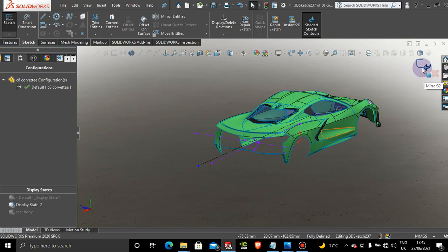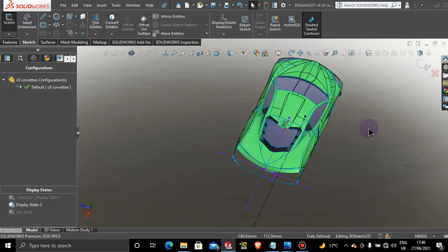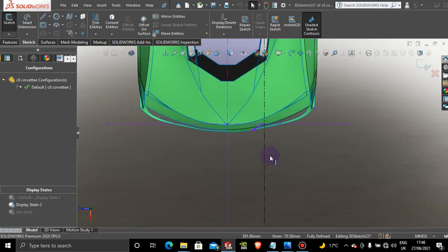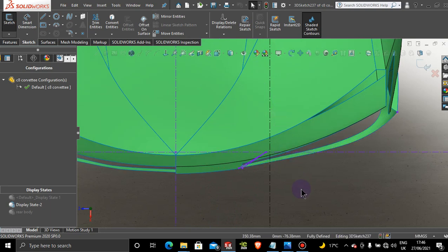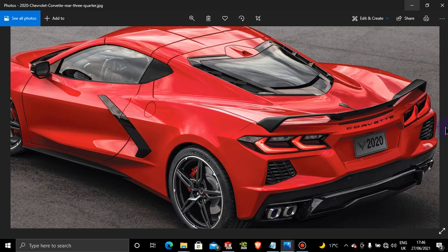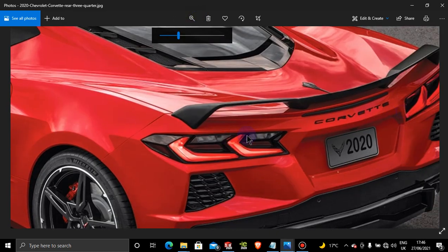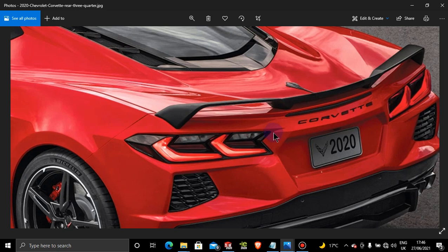Okay, and then I'm going to maybe not exit the sketch yet. Just going to jump to the top here. And that reference point that we need, the point that we're looking for, is going to be this point here. So obviously it falls underneath this surface edge that we have on the model, just a little bit, right?